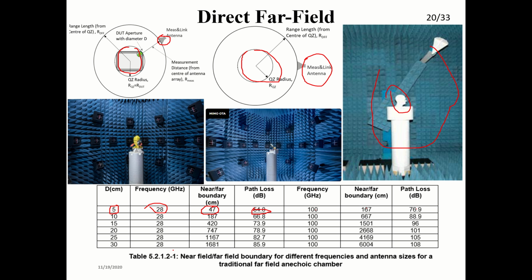When measuring in your system, you have to ensure approximately this path loss; it should not be too much, otherwise you will end up with wrong results. That's why it is given as a reference. If you are setting up a lab to test 5G devices, you have to ensure these values as minimum criteria, otherwise they will not certify your lab for testing 5G devices.